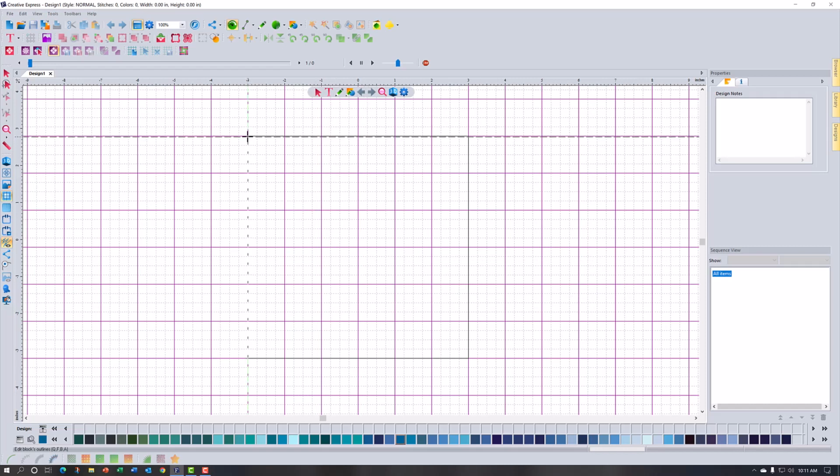And I'm going to come up to this corner and I'm going to click, and then I'm going to drag. Now I'm not holding down the mouse key. I just did a click and I'm just moving the mouse. So I'm not really dragging down to this lower corner. And then I'm going to click again to enter that point, and you can see it draws in that line. And now I'm going to press enter on the keyboard, and I apologize you can't see me doing this, but I'm pressing enter, and that tells the software that I'm done with that particular line.